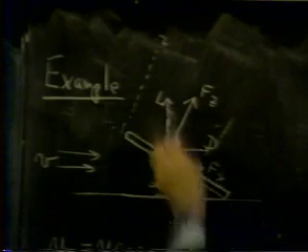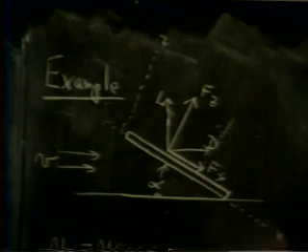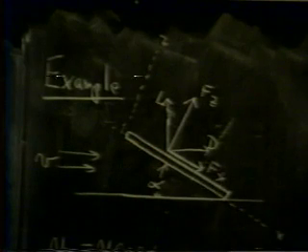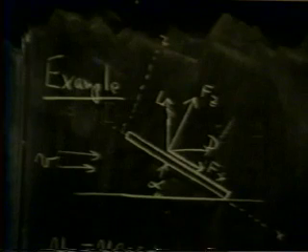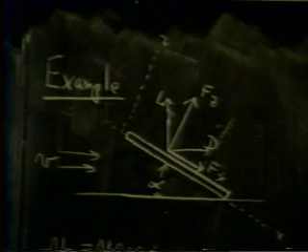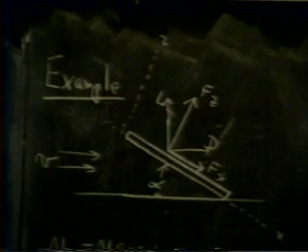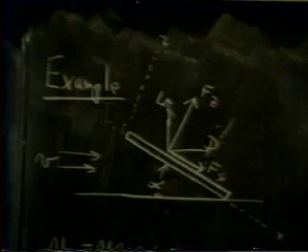The lift, that is the force going directly up perpendicular to the airflow, and the drag, the force against the airflow. And lift and drag are things obviously of interest to anyone concerned with aerodynamics. And the question is, what is the dependence of these forces on the various physical variables that are involved?